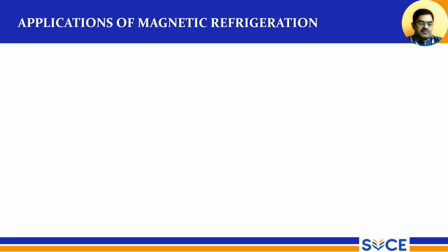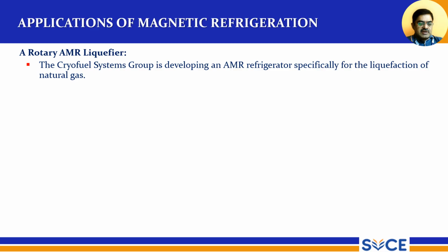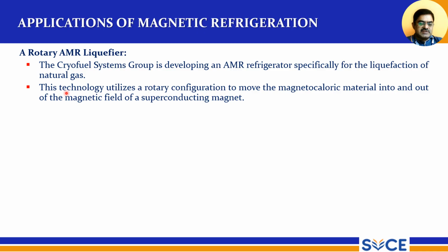So applications of magnetic refrigeration: a rotary AMR liquefier. The cryofuel system group is developing an AMR refrigerator specifically for the liquefaction of natural gas, and this technology utilizes a rotary configuration to move the magnetocaloric material into and out of the magnetic field of superconducting magnets.